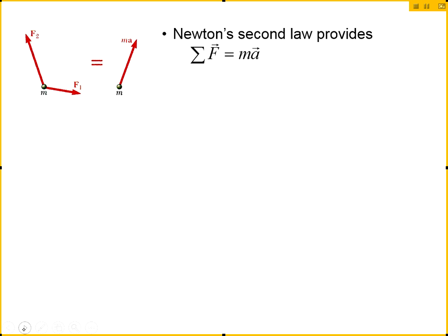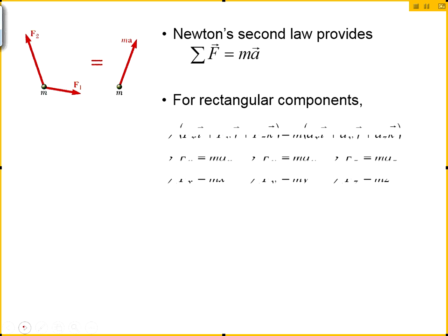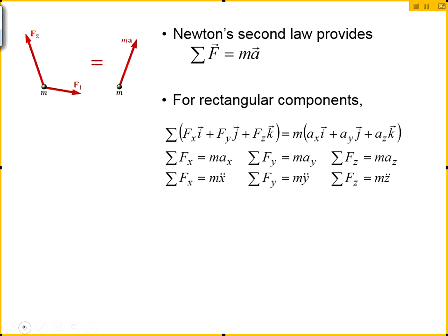And how do you decide which one to use? Yes, if you're given the radius or interested in the radius of curvature, use normal and tangential. If what's happening along X is sort of independent from what's happening along Y, you use rectangular. If you have something rotating and the length changing, it has to be radial and transverse. Okay. So in each case, if it's 2-dimensional motion, you'll have 2 equations, right? Oh, if it's in 3D, you just do a summation of forces in X, Y, Z independent of each other. Those are your 3 equations.